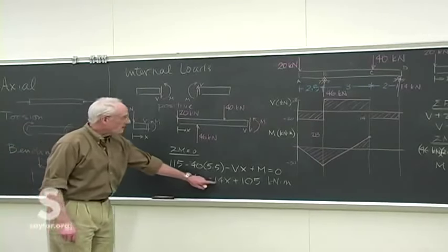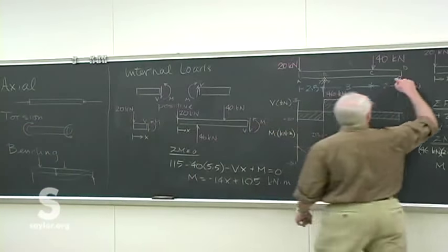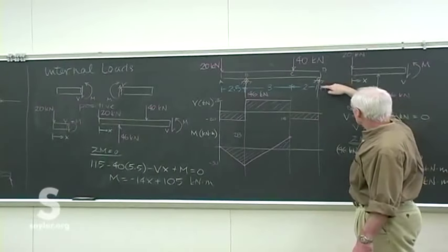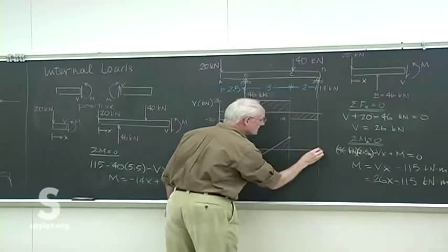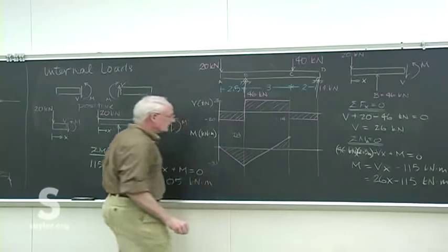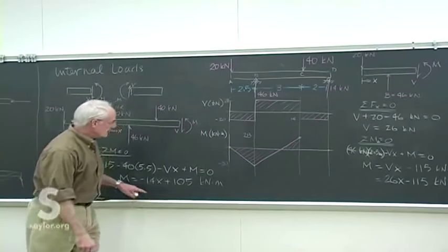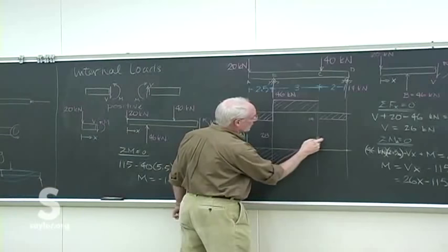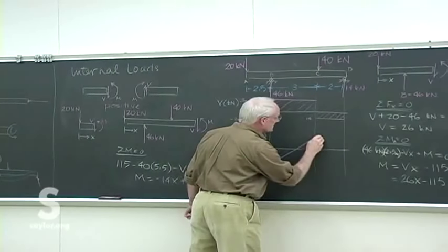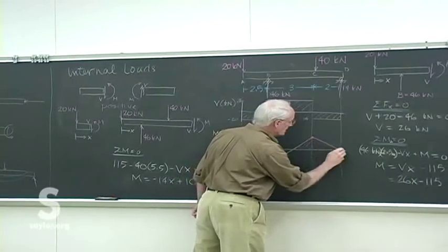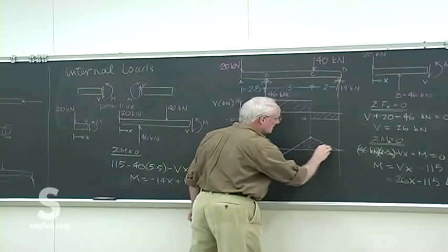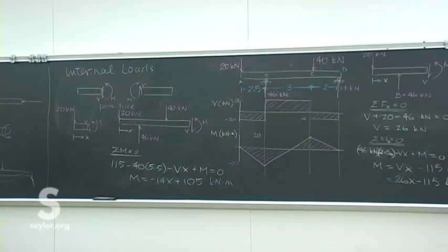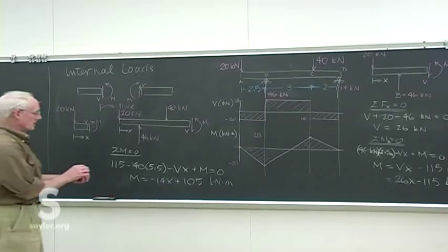Minus slope makes sense because we know we have to come to this roller support end, which will have no internal moment left in the beam. So we know we have to finish at 0. So the minus slope makes sense. And if we put the values in, we start exactly where we left off at the moment. And then we're able to finish our moment diagram.